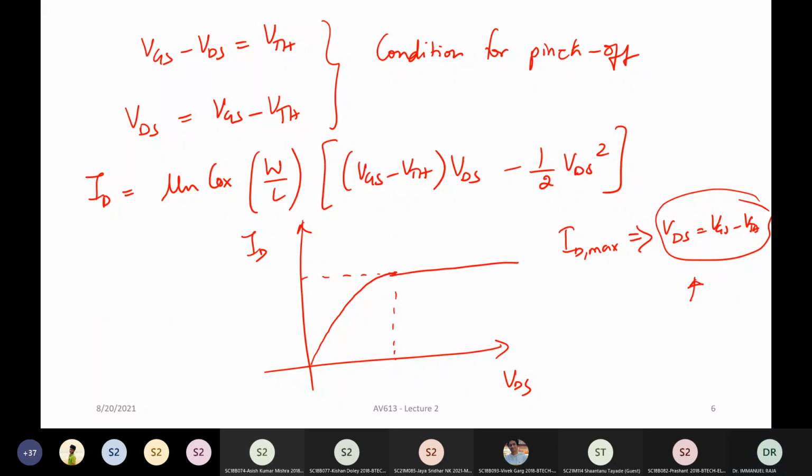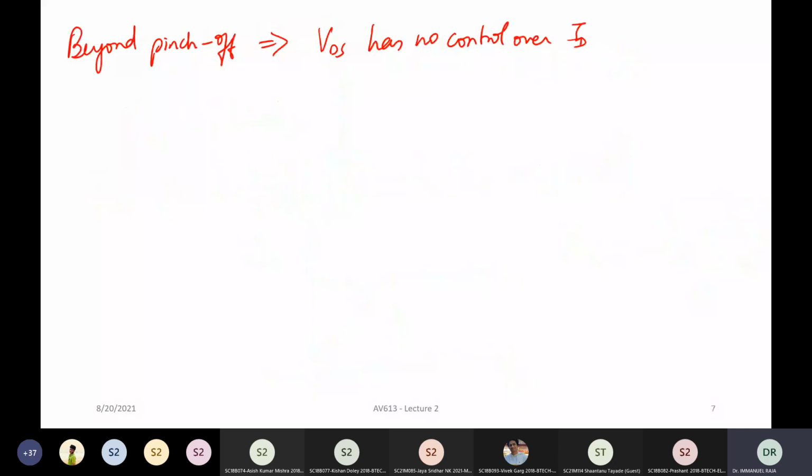All right. Now, this curve is something that all of you have looked at. This is very similar to the output characteristics of your BJT. And this is the same for your MOSFET also. All right. So here, if I were to redraw this curve, I can say that there is this linear region. So this graph I'm drawing between ID and VDS. X-axis is the drain to source voltage and Y-axis is the drain current.